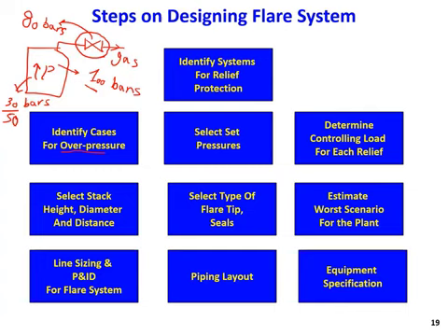For the flare, we have to consider all the sources of emergency relief and the worst scenario, and based on that we calculate the height and diameter of the flare stack. Then the type of flare tip and seals also has to be considered, as we have different types.